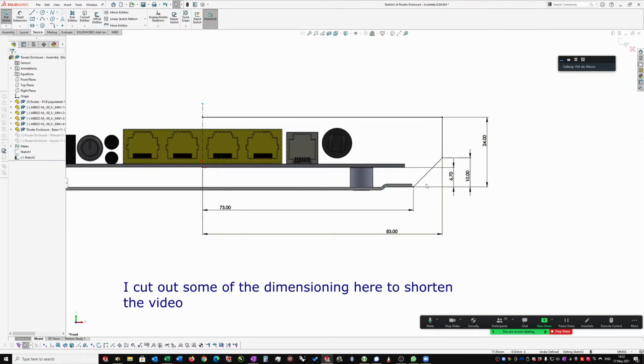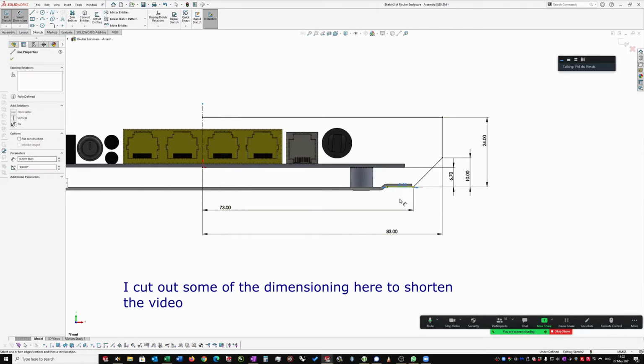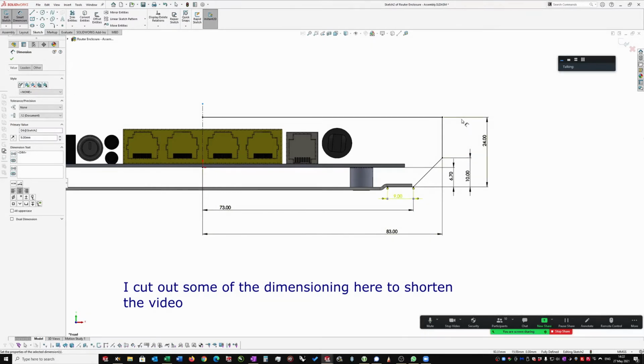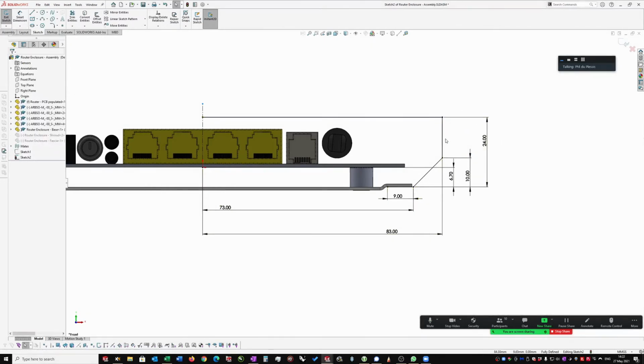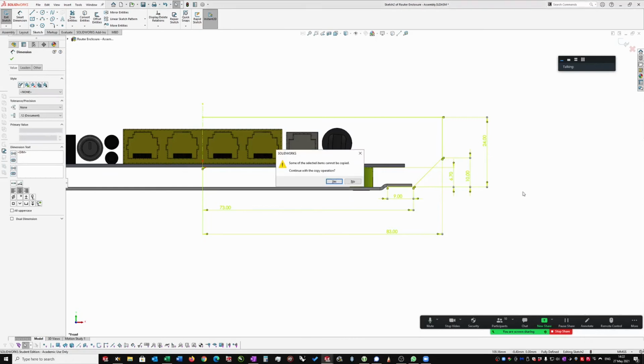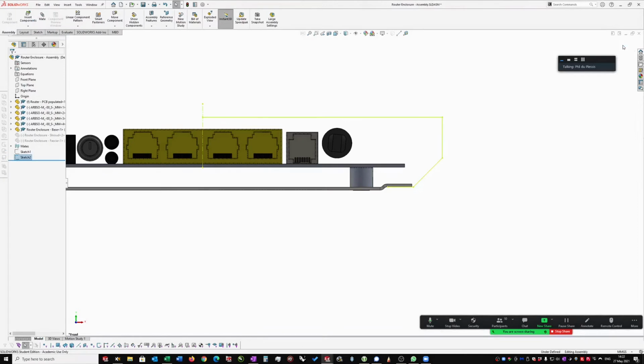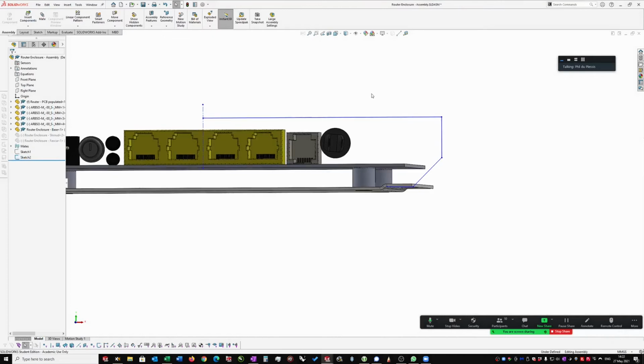When you do this shape that I'm showing you now, which we're going to use as the basis for the sheet metal, don't put any corners in, because the corners are going to be put in for you by the sheet metal command. So I'm going to select all of this and just say Control C. Don't worry about the warning message, because currently that sketch sits inside my assembly. It doesn't sit inside the part.